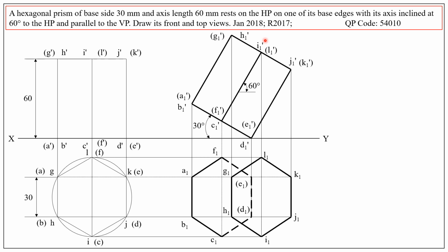So the final step left out is to draw the vertical edges, or the edges corresponding to the rectangular faces of the solid.